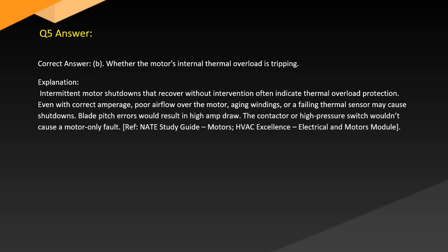Blade pitch errors would result in high amp draw. The contactor or high pressure switch wouldn't cause a motor-only fault. Ref. NATE Study Guide, Motors. HVAC Excellence, Electrical and Motors Module.